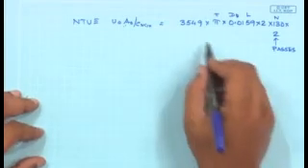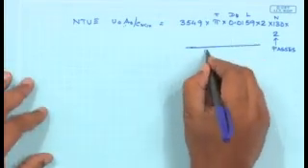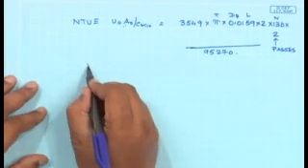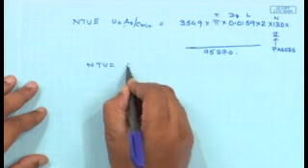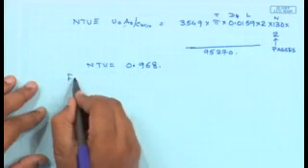So I have already calculated U naught. I now know what is A naught, and the C minimum I have calculated in the previous slide. So this C minimum is simply going to be the one which we have calculated earlier. So this NTU would be 0.968.